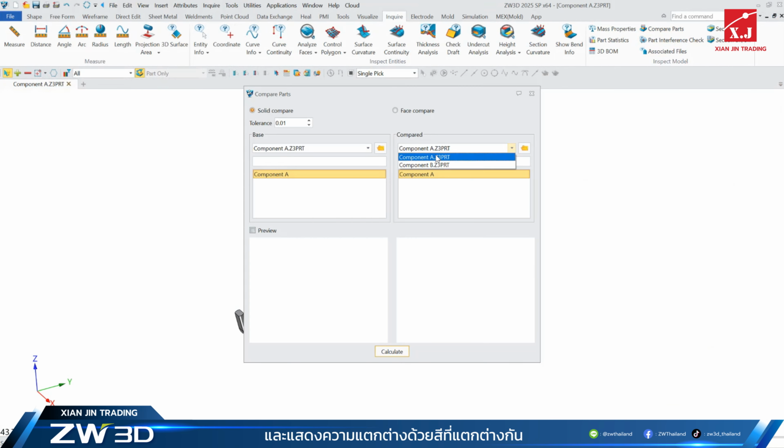Regarding 3D BOM in assembly design, ZW3D 2025 SP added the Legend property, enabling users to view thumbnails of assembly components in 3D BOM. This could help designers and their partners check the 3D BOM in a more intuitive way. When inserting standard fasteners in assembly, the Smart Fastener function is an efficient way to insert them. In the ZW3D 2025 SP version, we optimized this function to make it more convenient than before. Now it supports adding nuts and gaskets in batches for fasteners of different sizes, and modifying the length and nominal diameter parameters of fasteners in batches.